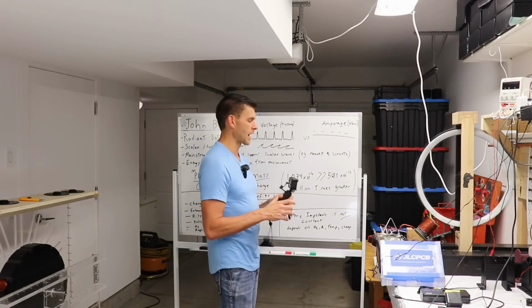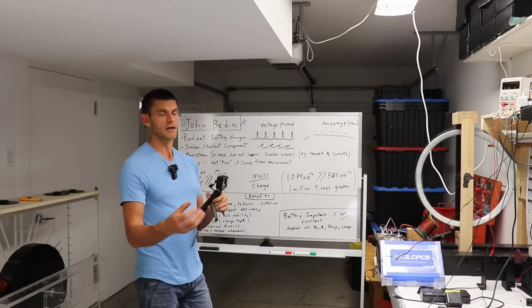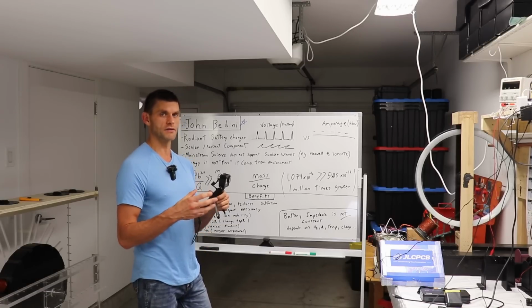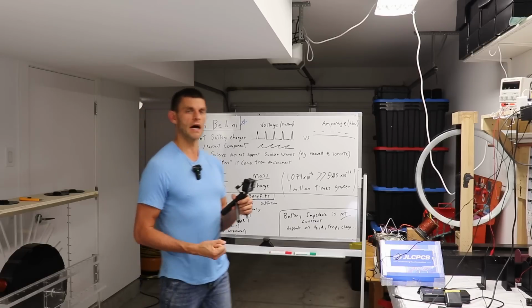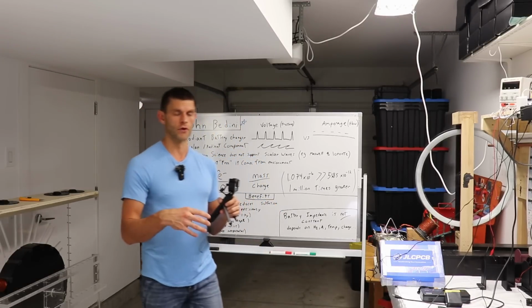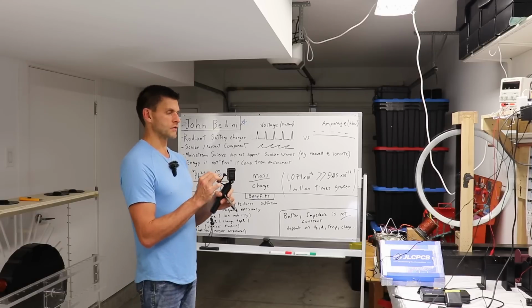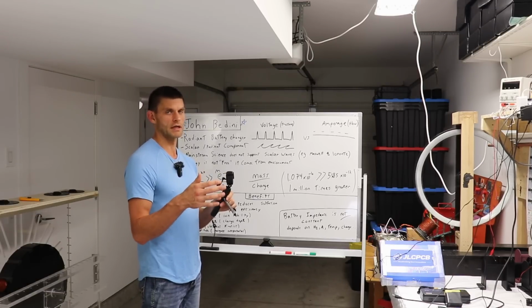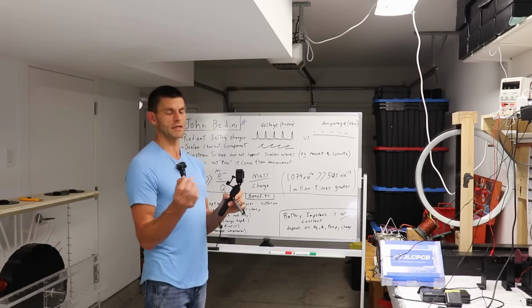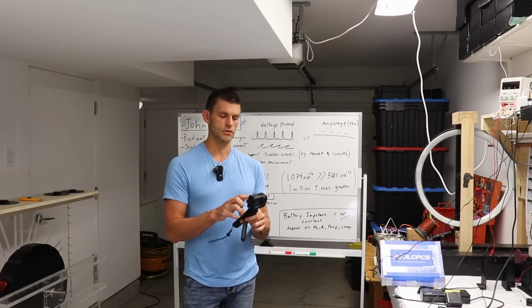It's called a lead acid battery, these particular ones, and it's called that because there's acid and then there's lead plates, and the lead ions are what form when it gives it a charge. So that's what we're drawing the energy from in the battery, are these lead ions floating around in solution in the electrolyte, the acid. Now, lead sulfate forms on the plates in between charging as a process of it. This is not good because then it means there's less lead ions in the electrolyte in order for us to draw potential charge from.